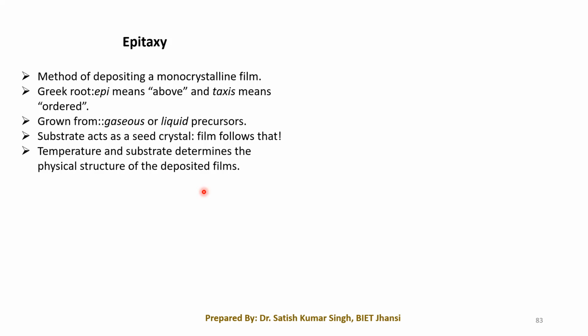It will have a certain resistivity, a certain amount of dopant that decides the resistivity, and a particular crystal orientation. So if your device requires some other parameters, and the parameters of the substrate are not suitable for fabricating your device, either you can go for fabricating a new substrate, or we can grow a layer onto the substrate of desired specification.